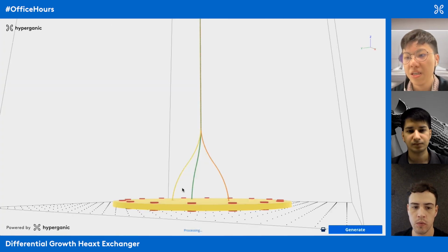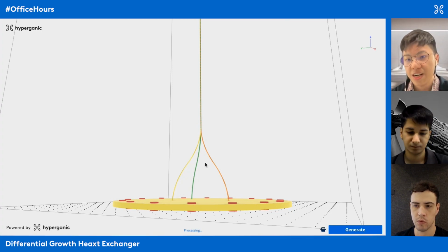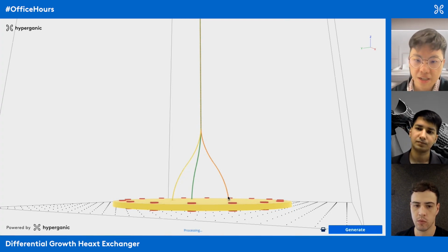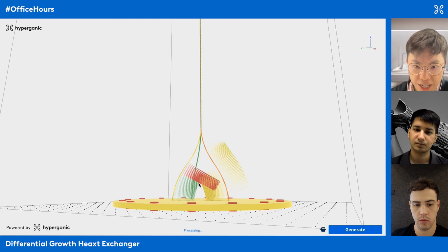What I'm really doing here is to simulate where the pipe collides and where the pipe is entirely encompassed within the other pipe. So based on this data, I'm able to formulate, let's say, as my pipe goes along here, maybe I start increasing this pipe at this particular region. So it will start increasing. Then you see that at this point it collides.